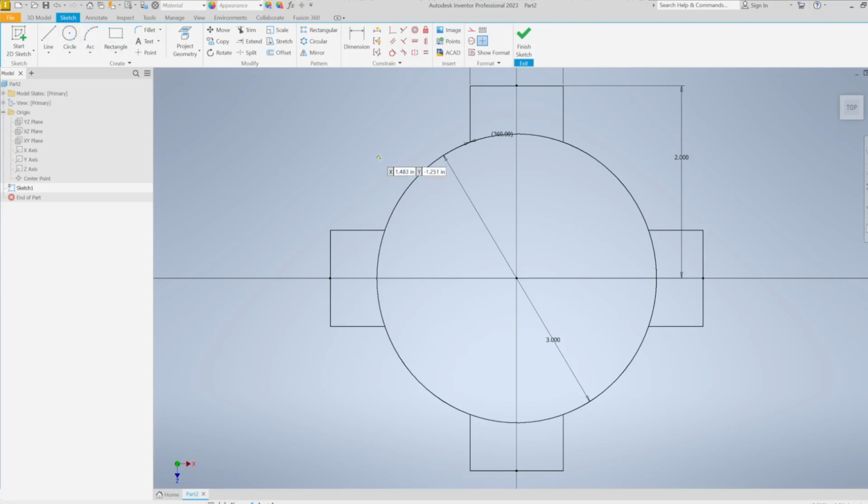Then I'm going to start making a circle. Looks like my circle is here. Right, it's going to be right above, right vertical to that center point. And I have a dimension for that of 0.5 diameter. Right, and there's going to be a dimension of 0.75 from the center. So I have 0.75 from here to here, 0.75, and now everything is fully constrained.